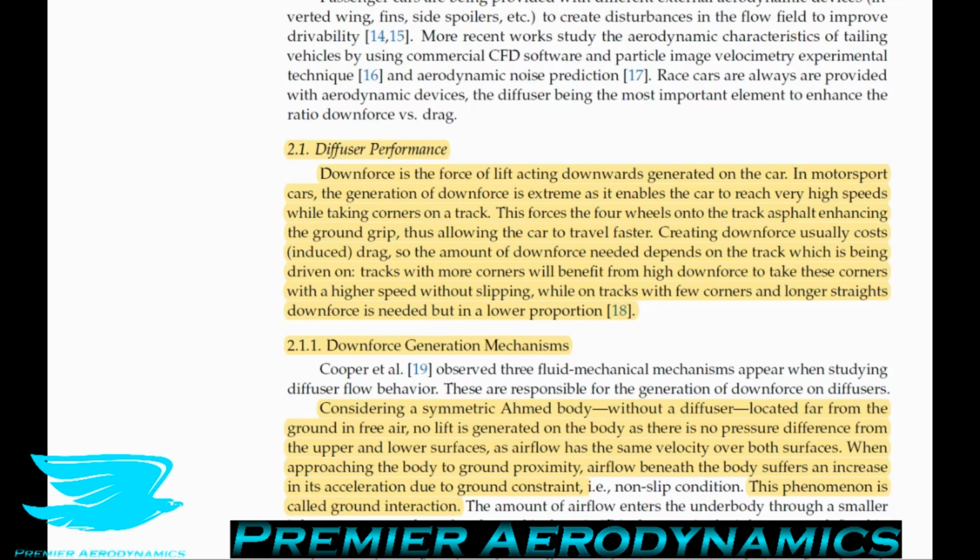So this is actually quite a tricky term to define in an aerodynamic sense in general, because each subfield in aerodynamics has a little bit of a different idea of what they call induced drag. To give an example, in aeronautical engineering, we always refer to induced drag as the drag arising from circulation changes. So induced drag has a very specific equation, which is related to the gradient of the circulation. In layman's terms, it means just how strong the wingtip vortices are. This is only ever produced when you have lift generation. That's why it's called induced. The lift is inducing this drag.